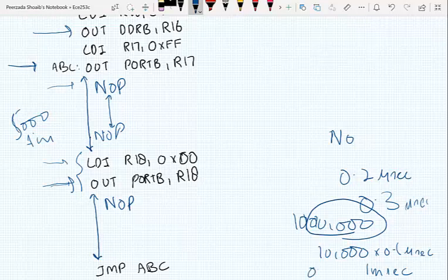I will have a time delay of 0.1 seconds, but I have to use it after both instructions: after turning the LEDs on here, and after turning them off. So by doing that, I will actually increase the time period of the blinking, so that the human can perceive this blinking. Now the question is, I can't in fact write NOP 5000 times or 100 times.